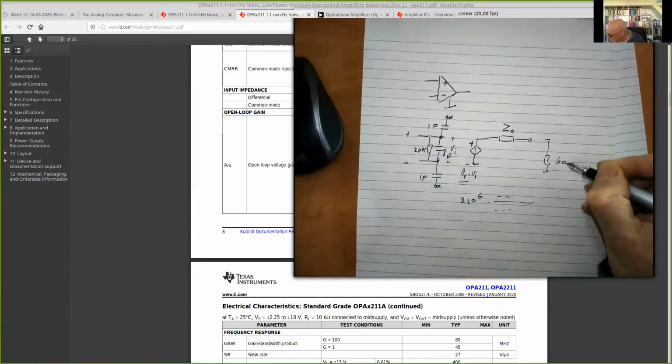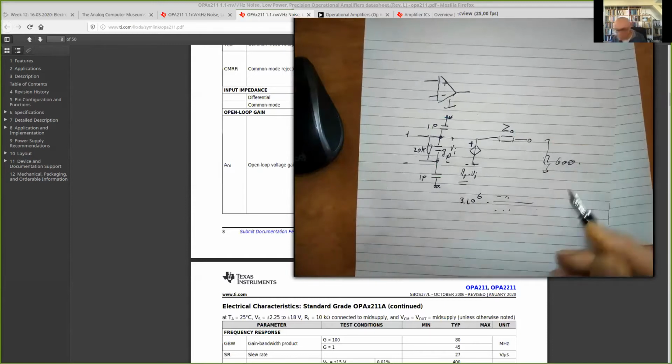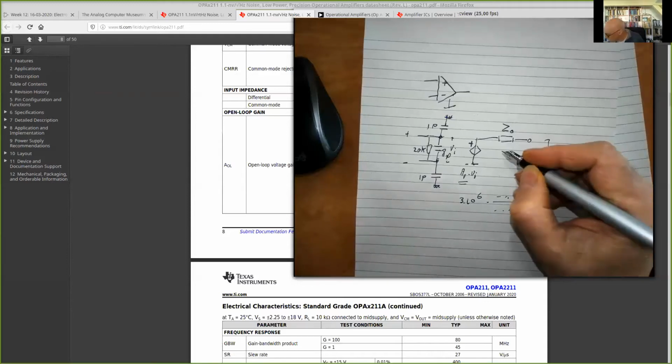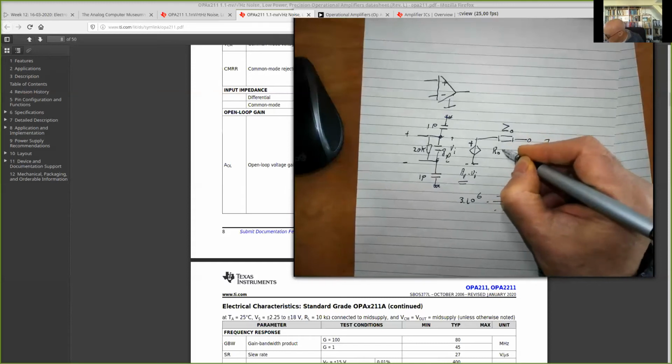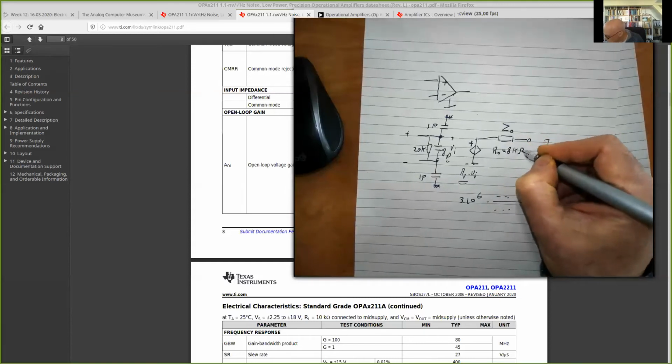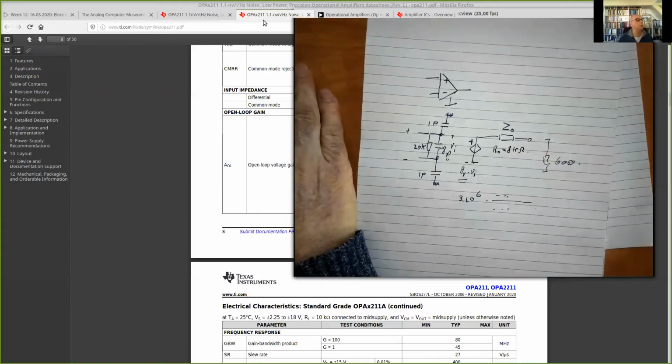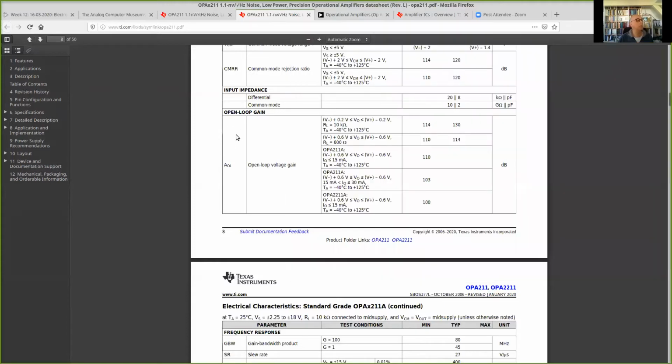600 ohm, that it drops from 3 million to what I said, 500,000. And if you calculate that, I think I remember the value, but don't blame me if it is not correct. Then I'll say RO equals 8 kilo ohm. So you find it from these numbers. And unfortunately, it's not always specified this way, but here I took an operational amplifier that has this specification. So we have numbers to determine the DC value of the small signal output impedance.